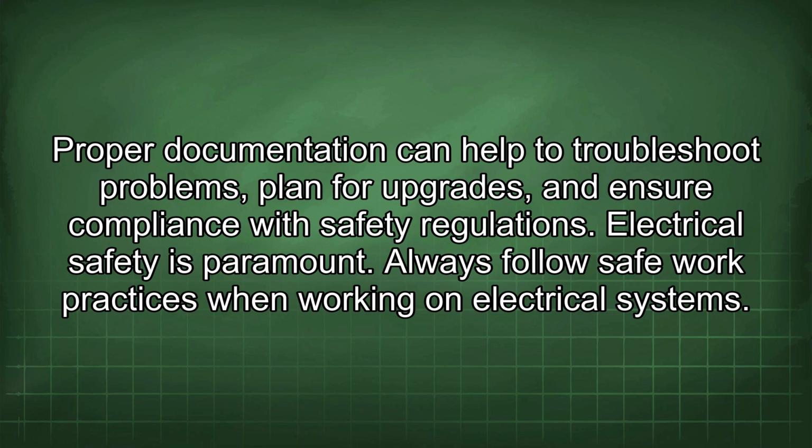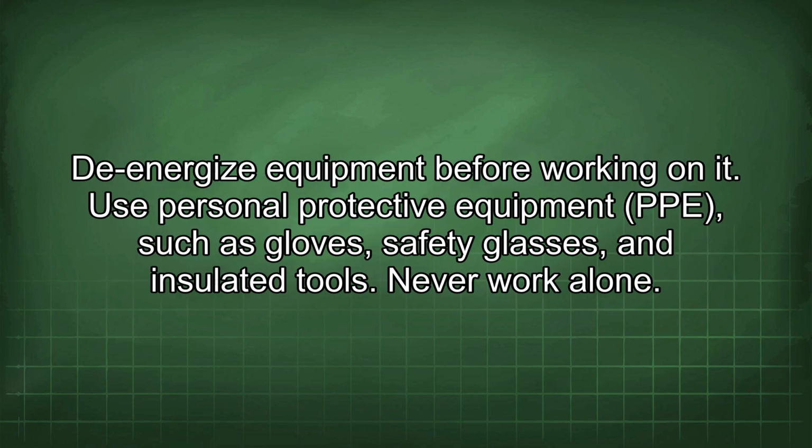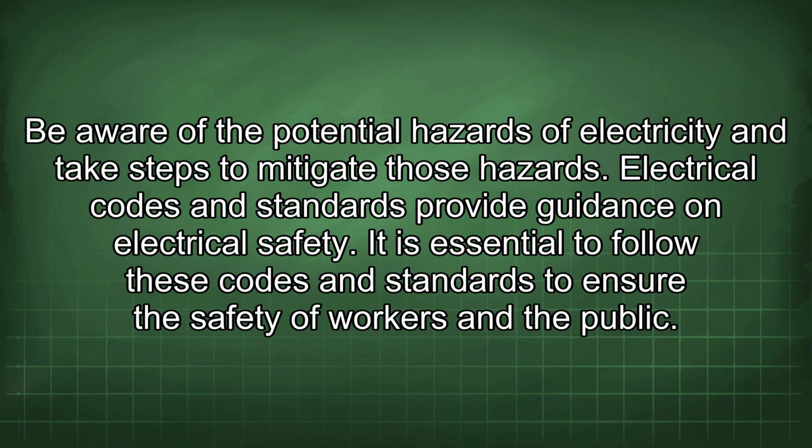Electrical safety is paramount. Always follow safe work practices when working on electrical systems. De-energize equipment before working on it. Use personal protective equipment (PPE) such as gloves, safety glasses, and insulated tools. Never work alone. Be aware of the potential hazards of electricity and take steps to mitigate those hazards.